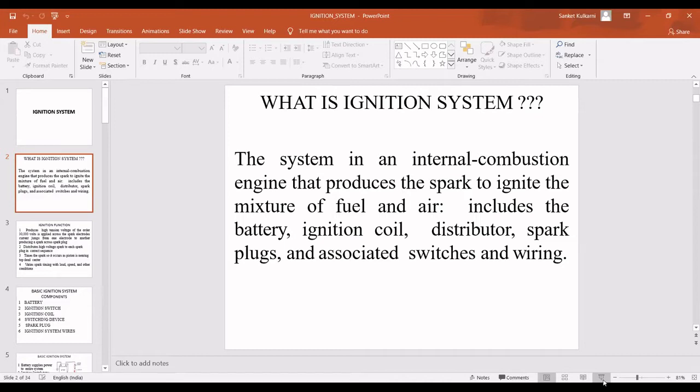Here the fuel injector acts as an atomizer, and diesel is injected at the end of the compression stroke in the form of fine spray particles for a particular crank angle rotation.